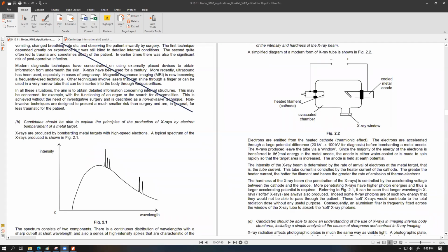And if you wonder why this electron would not be a problem, you should see that in this place, to operate this, we have connected this to a high DC supply. It means this is always maintained at a positive potential, so whatever electrons come and hit over here get absorbed to the source automatically, so this does not become negatively charged whatsoever.